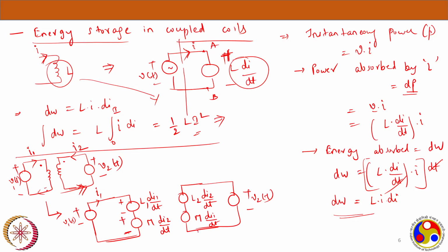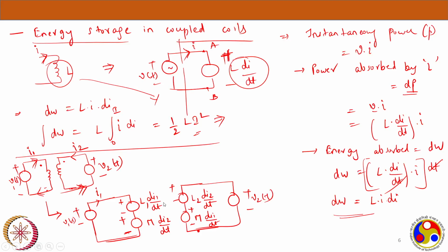If you are trying to get the polarity at this instant, and here the entering is positive and leaving is negative, so here also you are trying to get the same instant where it is leaving. So here it is negative and here it is positive. So here it is anyway plus and minus. That's how we get the equivalent circuit on both sides, if you are assuming two sources on both sides.